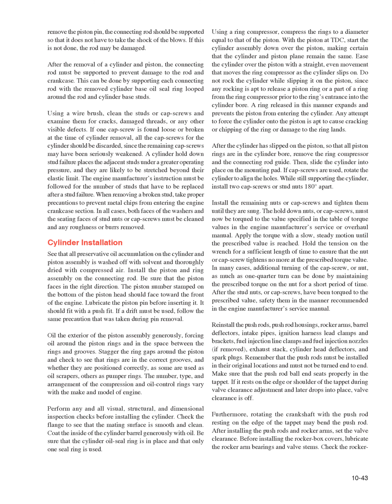Using a wire brush, clean the studs or cap screws and examine them for cracks, damaged threads, or any other visible defects. If one cap screw is found loose or broken at the time of cylinder removal, all the cap screws for the cylinder should be discarded, since the remaining cap screws may have been seriously weakened. A cylinder hold-down stud failure places the adjacent studs under a greater operating pressure, and they are likely to be stretched beyond their elastic limit. The engine manufacturer's instruction must be followed for the number of studs that have to be replaced after a stud failure. When removing a broken stud, take proper precautions to prevent metal chips from entering the engine crankcase section.